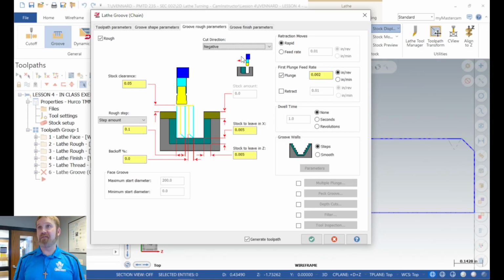I don't see any benefit unless they can sell me on something that the bidirectional is a better option as far as tool life or cutting parameters go. I guess it makes sure you're using all of the insert, because when you're going negative, you plunge with the whole insert and then you're just using that same 75% as you go over.